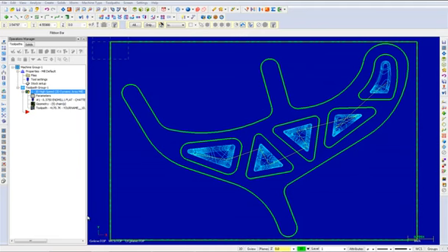In this video, we will copy the toolpath and use the dynamic rest mill toolpath on all the pockets. The first thing we will do is copy the toolpath. In the Operations Manager, make sure that the toolpath is selected. This will be indicated by a green check mark. If your operation is not selected, click the Select All Operations icon here.